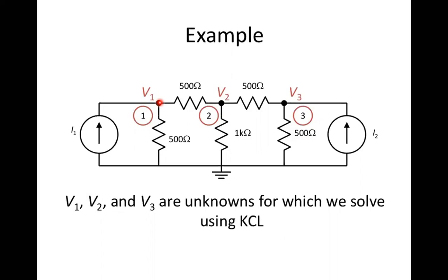So I is nothing but what? V is equal to IR, so I will be equal to V by R. Here at this particular node, we will have an equation because we are finding out a node voltage at particular V1 at particular point A where the node voltage we have assigned as V1. So here it will be V1 minus V2 divided by the value of this resistance. This is R2. So V1 minus V2 by R2.